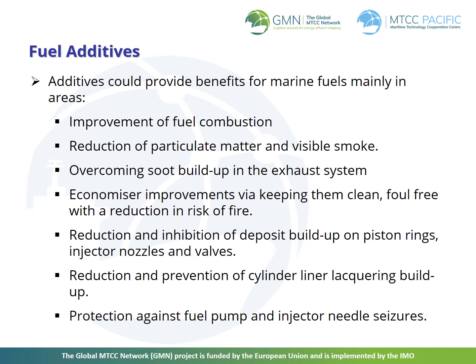As a result of low sulfur regulations, the composition, the long-term stability, the lubricity, and the combustion quality of fuels are evolving due either to the desulfurization of heavy fuel oil or blending. Fuel contamination with bio-related products mixed with fuels adds a new dimension to fuel's long-term stability.